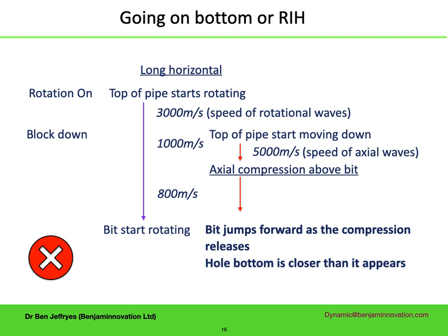Running into hole, there isn't a hole bottom to hit, but as the block will normally be going down a lot faster, it's a lot more motion, and you can have a great deal of compression in the pipe above the BHA.